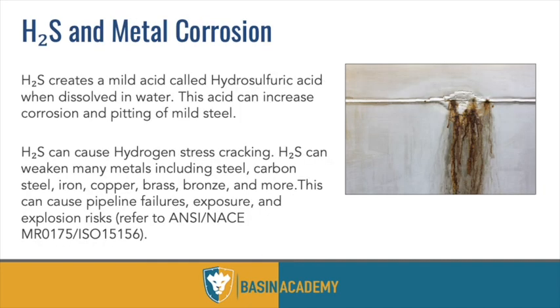So again, I kind of mentioned this on the last slide, how hydrogen bonds with harder metals. A lot of times, tanks will be lined where we know there's going to be H2S. They'll use different metals that aren't as porous, so that H2S can't bond with the metal. There's a lot of different tactics we can use when we know we have H2S. The problem is, in our industry,